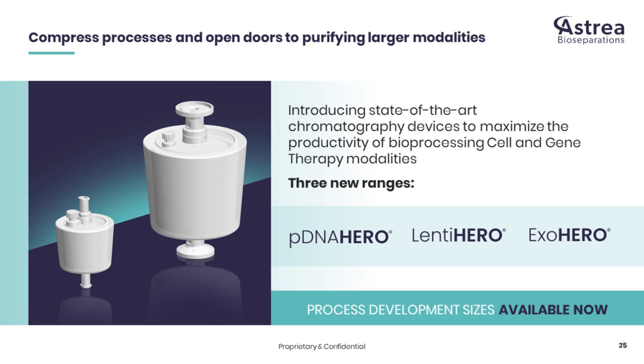Our first question is, what are the unique properties of your Astrea Adept nanofiber compared to other fiber membranes? Yes, our nanofiber is composed of two different materials, one that gives strength and another for flexibility. So the effective size of the path through the fiber mat we made is much larger than other electrospun fibers. And our fiber is flexible compared to others, so it's possible to fit it into a radial flow device, which can be easily scaled up.